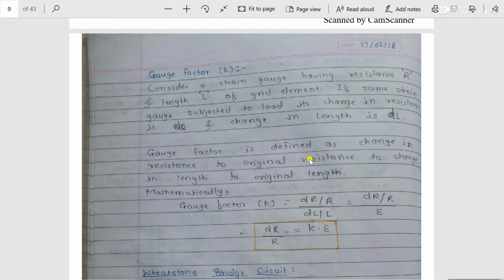we have to consider this constant factor, which is called the gauge factor, and this gauge factor is one of the constant values. Sometimes it depends upon the resistance, and the gauge factor is available in the form of gauge factor equal to 2, gauge factor equal to 2.5, gauge factor equal to 3. Like that, constant values we have to set in the strain gauge applications.